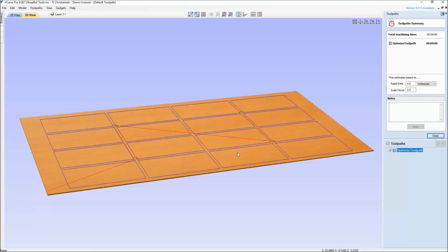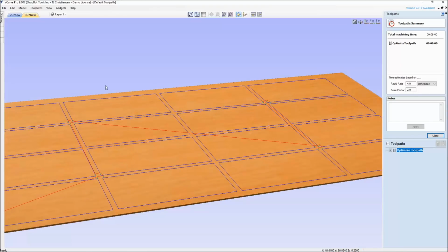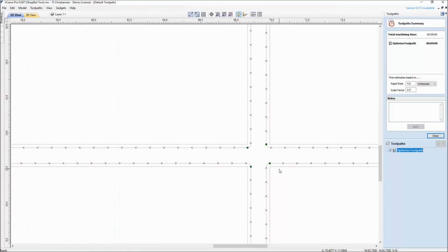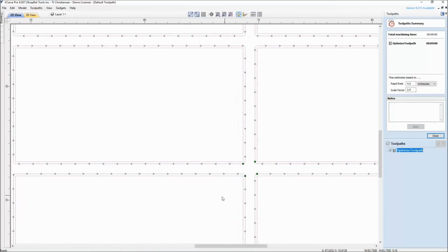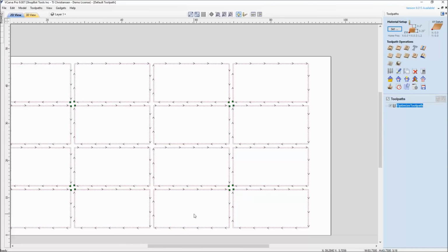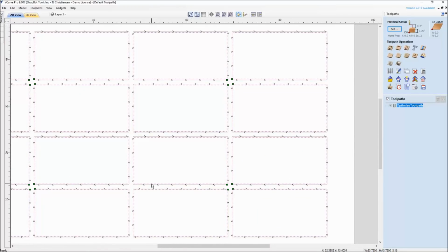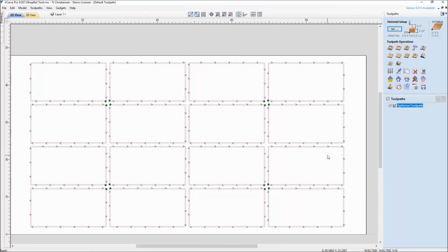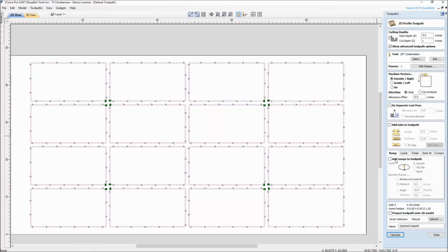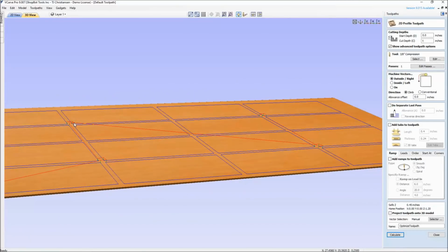So again, now it comes to the point of, we're saving 5 seconds. Is 5 seconds worth saving where you really want your cut to be from that corner? Other people, depending on your type of cut or your material, may not want to use that corner as a cut. Some people like to put their start points out here in the middle so that when they ramp in, it's not built off a corner. But what we're trying to show you with this first part is you have the option of moving your start points. The less red you have up above your part moving back and forth, the less time the ShopBot spends just traveling from point to point. So moving start points is one, and now let's get into looking at ordering of the cut.